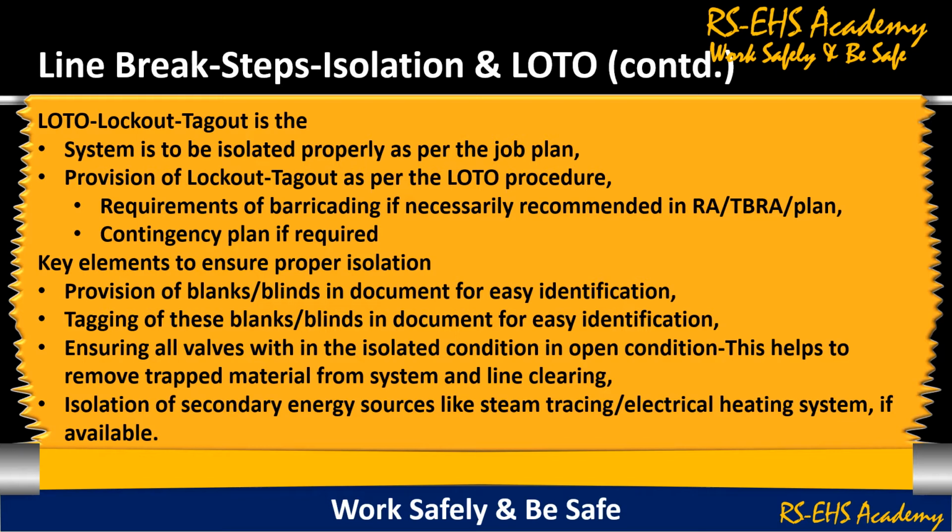Provision of blanks or blinds in documents for easy identification. Tagging of these blanks or blinds in document for easy identification. Ensure all valves within the isolated condition are in open condition. This helps to remove trapped material from the system and line clearing. Isolation of secondary energy sources like steam tracing or electrical heating system, if available.